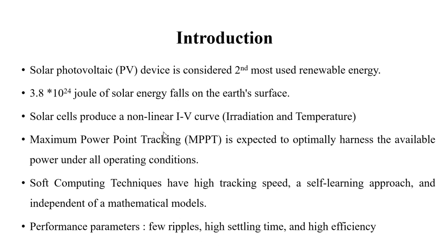The solar cell has a non-linear characteristic, which means the IV and PV characteristics are dependent upon the irradiation and the temperature. Whenever the irradiation and temperature vary, the maximum power point of the system changes. So to track the maximum power and extract it with a higher efficiency, we use the MPPT technique.